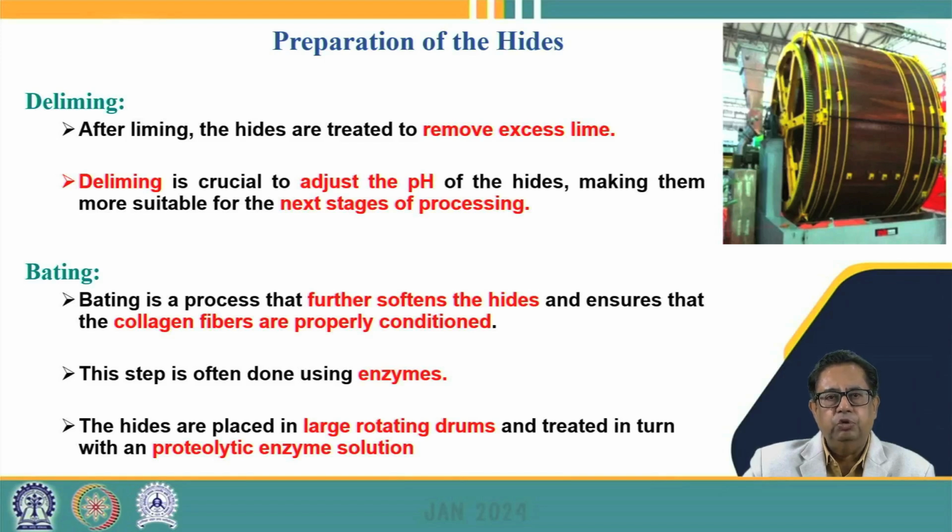For example, we may use proteolytic enzyme solutions, which dissolve the proteins and convert them into simpler compounds, which can then be discharged into the wastewater. So here the hides are placed into large rotating drums, which you can see on the right. These types of drums are used. Here we place the hides and the enzyme solutions, and they are rotated for a long time so that the proteolytic enzymes get enough time for the bating process to be completed.